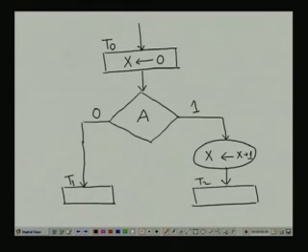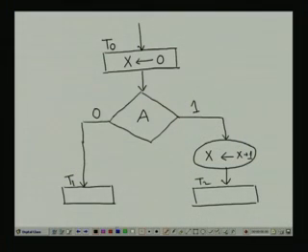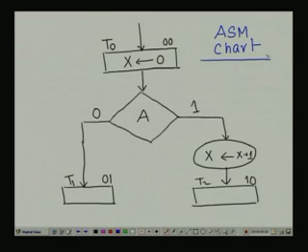And this is T2. Now, if we give a binary code, say we have 3 states T0, T1, T2, we need 2 bits to represent the binary code. So, T0 is 0 0, then T1 is 0 1 and T2 is 1 0. So, this is my ASM chart of an arbitrary simple state machine. Now, what will be the state diagram for this ASM chart?